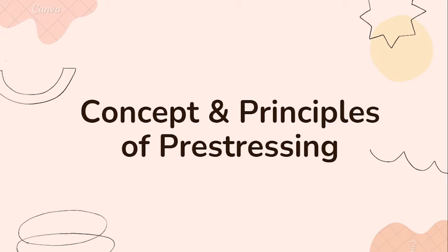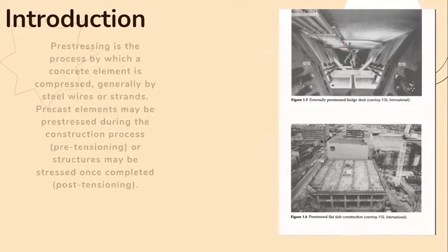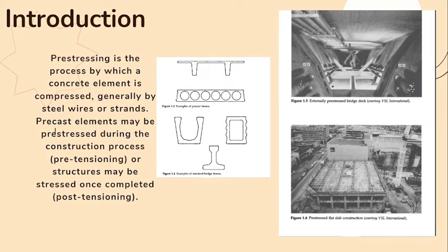Concept and Principles of Prestressing. Introduction. Prestressing is the process by which a concrete element is compressed, generally by steel wires or strands. Precast elements may be prestressed during the construction process, pre-tensioning, or structures may be stressed once completed, post-tensioning.